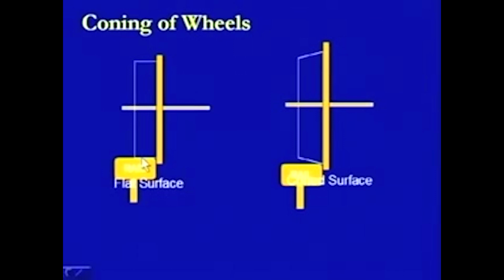Therefore, there are certain problems associated with flatter surfaces in the rail sections, because the rail section, as we found here, is a steel section, and this is also a steel wheel base, and therefore the interaction of these two creates many large stresses at this location as well as at this location. Whereas in this case there is a sort of slipping condition which gets created, and this wheel keeps on moving this way or this way, that is in the lateral directions.